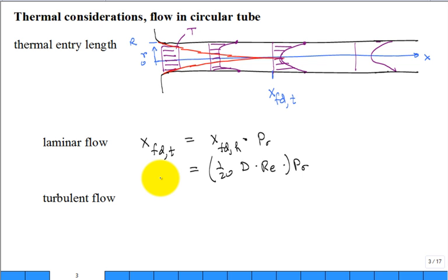Looking up again at the thermal entry line, yeah. Will at any point, with like an infinite length of tube, will the profile just disappear? No, because what I'm thinking is we're always pumping heat into it. But yes, after a while, let's say that it's a constant wall temperature, and the bulk temperature everywhere inside could go to a flat, uniform temperature profile, yes. But as I sketch it, I'm always pumping heat into it. But if you make it real long and the constant surface temperature, yes.